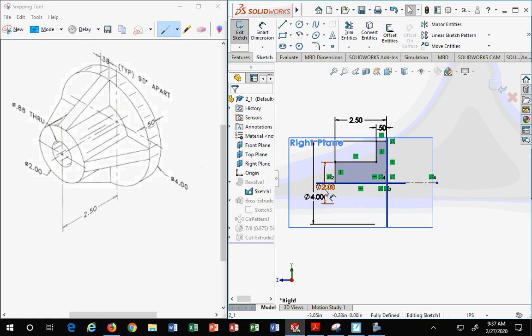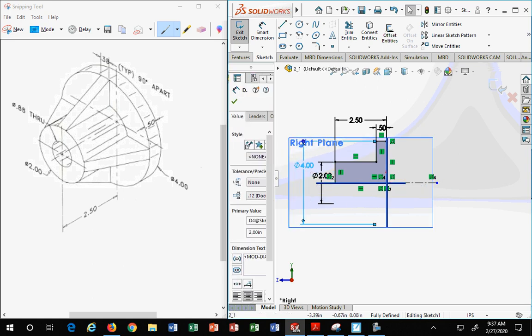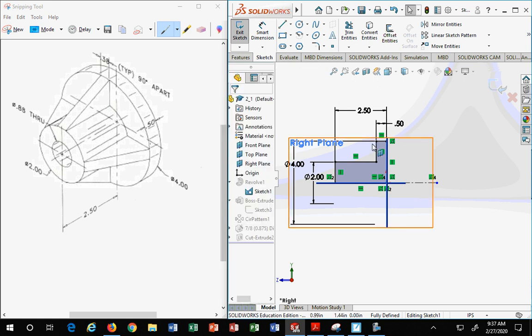Again, if you do not have any dimensions, like here we have the dimensions, remember? Told you, do not delete your dimensions. Now, you can intentionally position these dimensions out in a nice format. Trust me, whatever format you have for your dimensions in your base model, you will have the exact same format in your detail drawing. So if you remove your dimensions from your base model, you get nada on the dimensions in your detailed drawing. So, yep, which is bad.